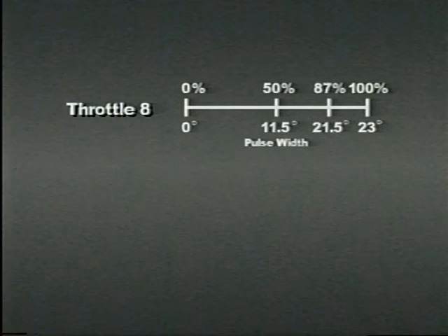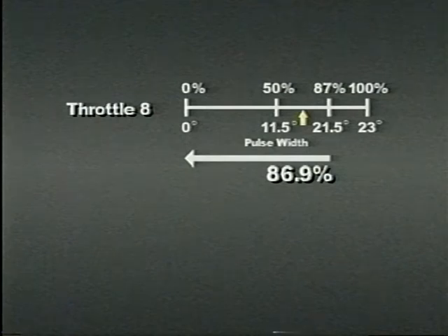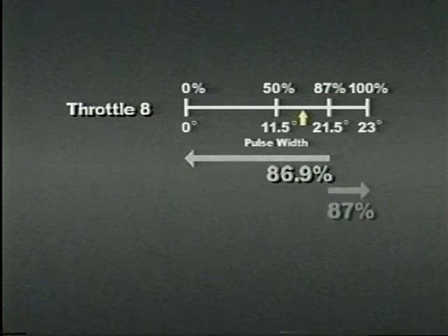The EM2000 looks at the engine ratio, and if the signal remains below 87%, will consider the engine healthy and capable of making rated horsepower. The excitation or load level on the generator will be governed accordingly.